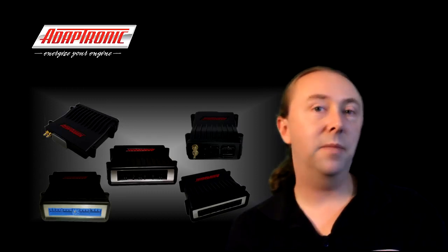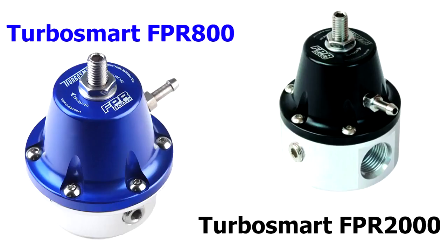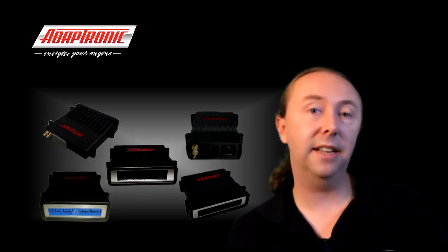In every situation where that's happened, they've swapped the regulator out and it's been perfect when they put in a brand new FPR 800 on it. So just imagine how much time the tuners would have spent trying to get good maps into the ECU and complaining about inconsistency of lambda and so on if that information wasn't there. When the information's there, it's a very quick diagnosis to do, especially because fuel pressure makes such a big difference to the amount of fuel that actually gets delivered.